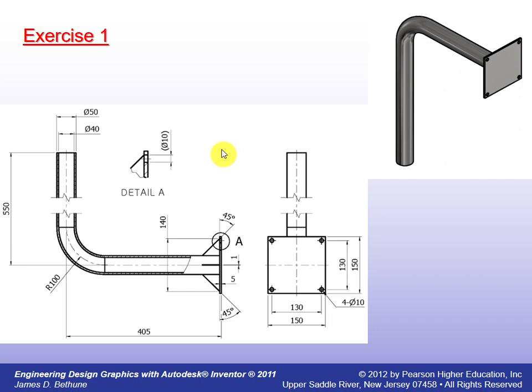Give me suggestions. We can use sweep for the pipe, very good, by drawing 2 circles in a plane, and drawing the path on another plane, sweeping the 2 circles, the area in between, along this path, and we will get the pipe. Then we can use the plane of the circles to draw a square on it, and then extrude the square to the thickness, and then go on. We finished the pipe now.